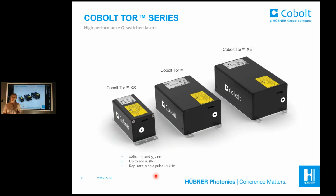The name of Tor XS stands for its small size. So it's a compact Q-switch laser. It's available at 1064 and 532 nanometers with energy in infrared up to 100 microjoules. And the repetition rate can be changed from a single pulse up to 1 kilohertz. Tor lasers are available at 3 wavelengths, 1064, 532, and 355, with an energy up to 150 microjoules for infrared. And the repetition rate is fixed at 7 kilohertz.